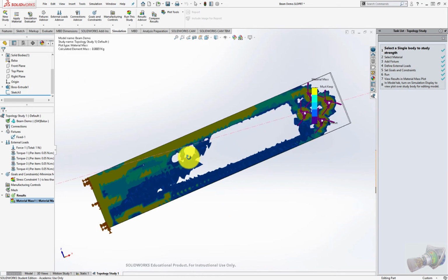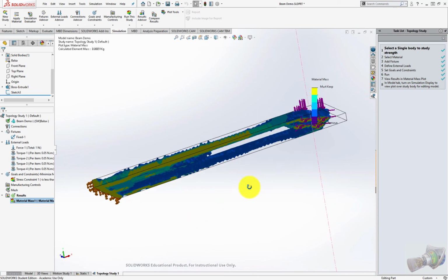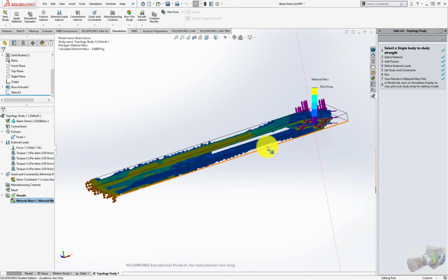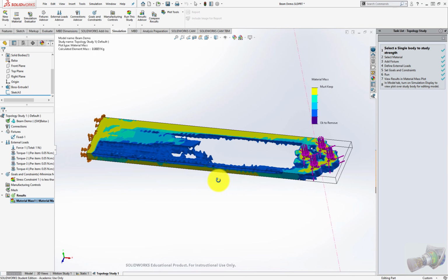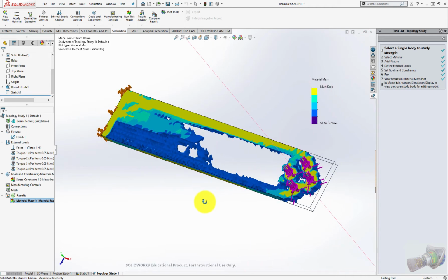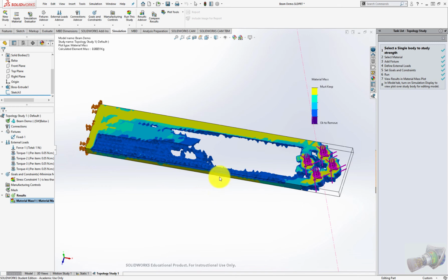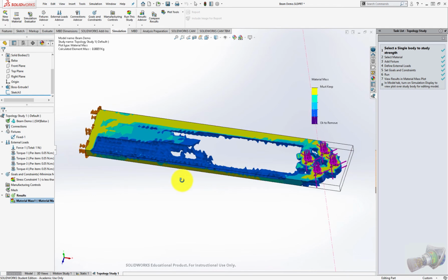Underside, yeah, not a lot to learn there. I would probably just keep looking at the top side. What I do want to point out though is look at how the simulation made this edge thinner on the bottom and made this edge thinner on the top. That's probably due to that reaction torque and how it needed to be stronger on one side than the other. So that's interesting. So anyway, that's what you would do with this: you would take this, draw inspiration from it, and try to recreate it with something that looks a little bit more like traditionally manufactured. No one's going to want to show up with a drone arm that looks like this, even if we could make it. It would just look terrible. Look like somebody chewed it up. So that would be the next step.